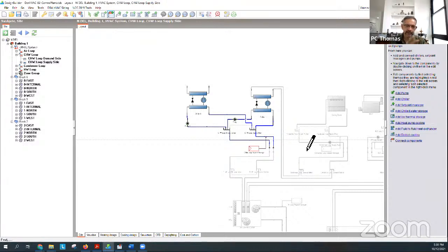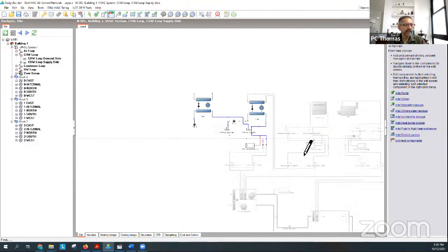So supply return header, two chillers plumbed in parallel, each with its own pump. Now the second chiller is also water cooled, so I need to connect the cooling tower to it. Now if I was going to do a second cooling tower, I'd do something very similar. Clone the cooling tower, put a separate pump on each one. For today I don't think we'll have the time, so I'll just have one cooling tower and I'll connect that